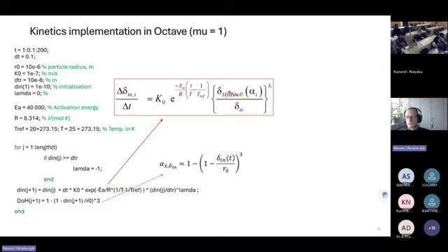So then the thicker the shell, the more you reduce. You have a factor which is less than 1, so you are reducing your rate equation. And this is the fundamental description of the diffusion, but for the planar case, which is just an approximation of the sphere. So you can improve this if you take the better equation for the sphere. But no need to improve, because anyway, this is just an approximative model,